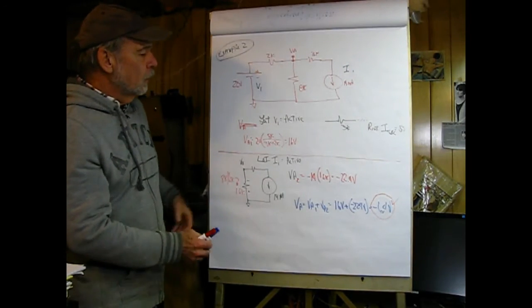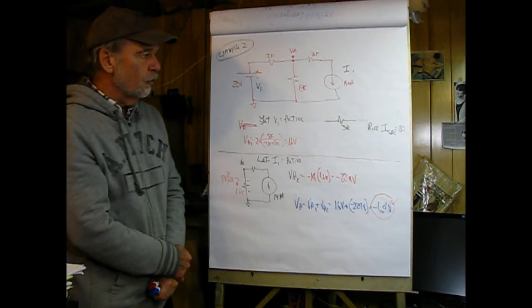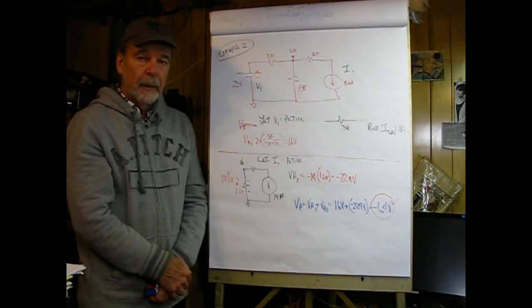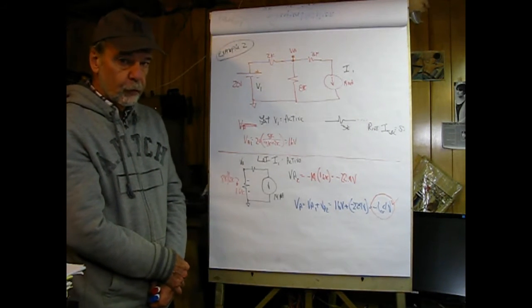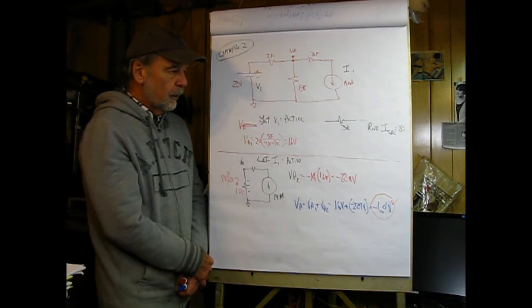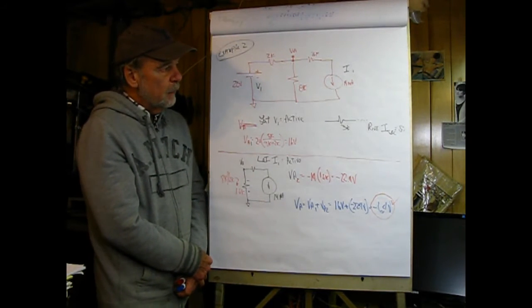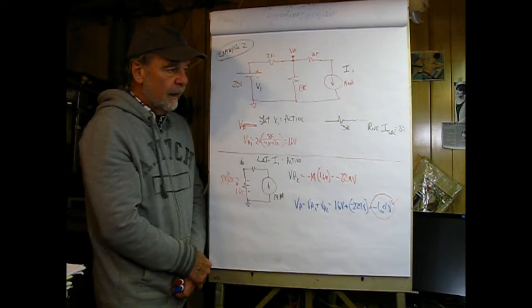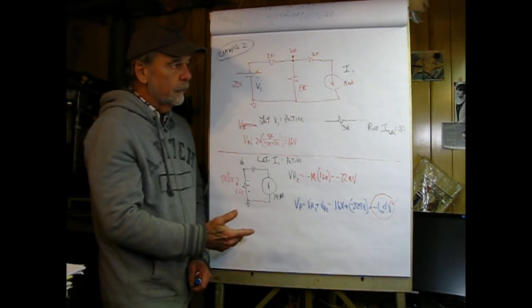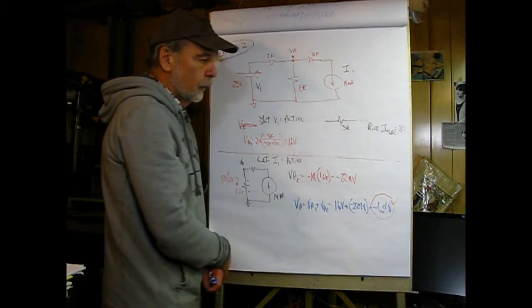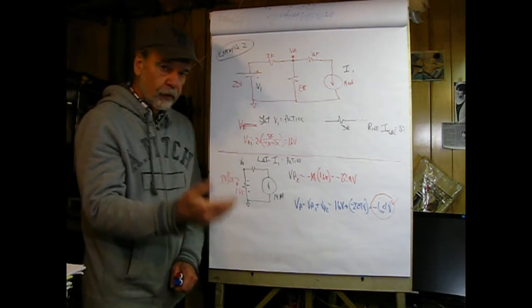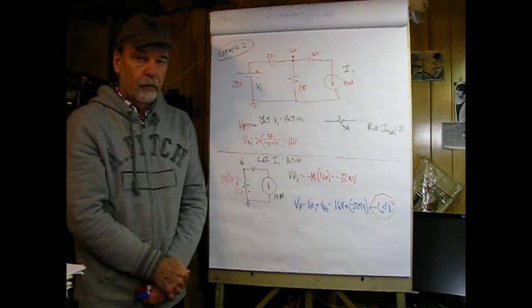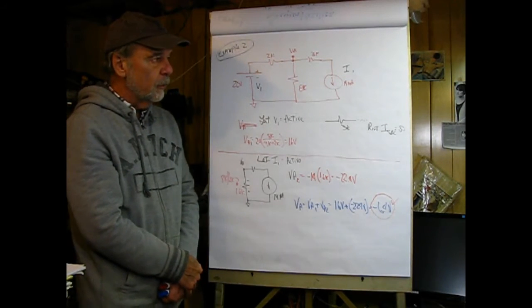So let's take another look, only this time we'll have a current source involved. I'm going to start by letting V1 be active, and there's no magic to that. You can let whatever source you want to be active first. We're going to find a partial response again, and this time, instead of replacing the source with a short circuit, since it's a current source, I have to replace it with an open circuit, which basically says that R internal is equal to an infinite resistance, meaning realistically that no matter what the voltage is across the source, the current is going to remain a constant 14 milliamperes.